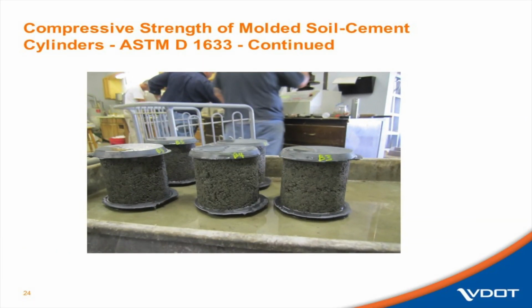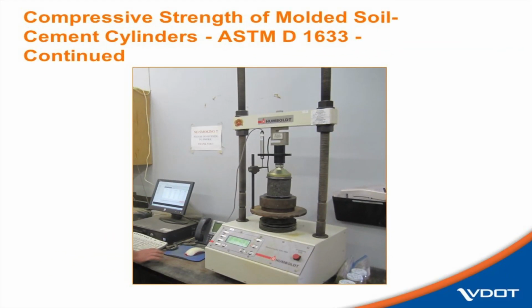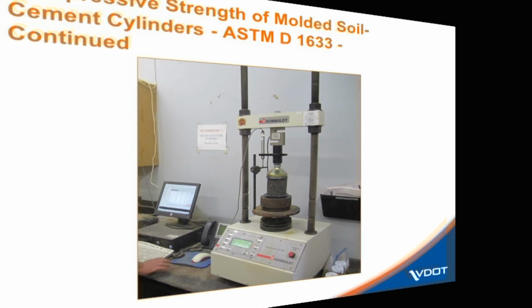A nice picture of samples ready to be tested. You can see that they're wet. They just came out of the soak tank after 4 hours. They've been sulfur capped. They're all well labeled, so you're not going to mix up samples. This is a typical Humboldt load frame, 10,000 pound load cell. This is a measuring gauge to figure out the rate of loading. Great little piece of equipment. This needs to be used in lieu of the big 500,000 pound concrete test machine.